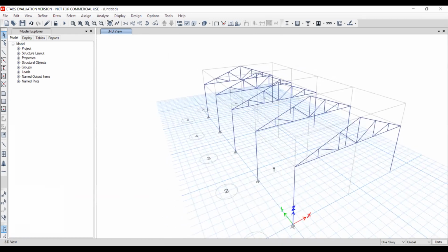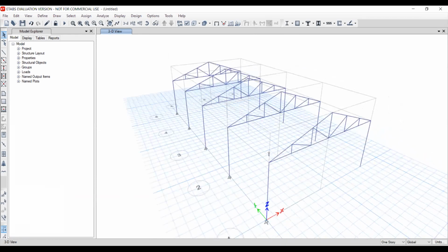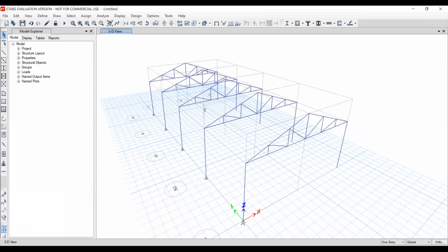Now after this, you have to connect in between these trusses. There should be beams. Those beams are called purlins. Actually we have a problem here: when we go to the real frames, on top of these purlins there will be sheeting. That sheeting distance will be up to 1.5 meters, maximum 1.5 meters. So you should check that carefully. What is the span of this member?